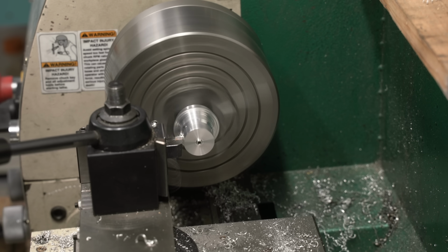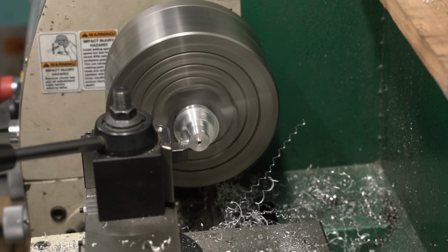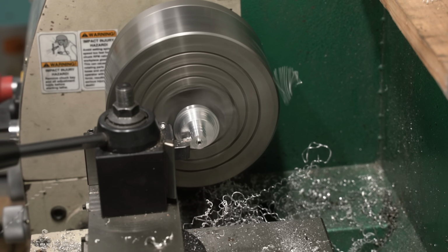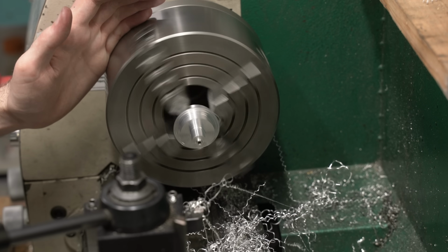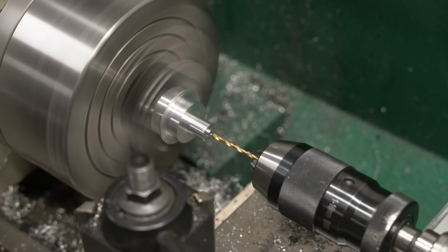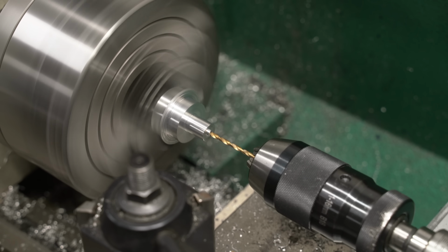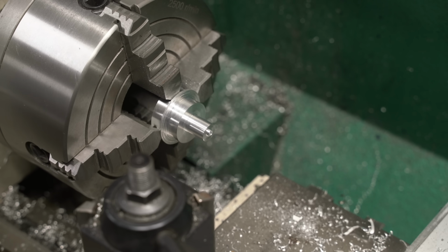While I'm here, I'm going to use the lathe to remove as much of the unwanted material as possible. I find that when it comes to small machine tools, lathes are generally faster than milling machines at removing material, so this will also save me some time. After that's done, I use a slightly larger drill than before and drill just a few millimeters in. This will form the step where the TEM grid will rest.